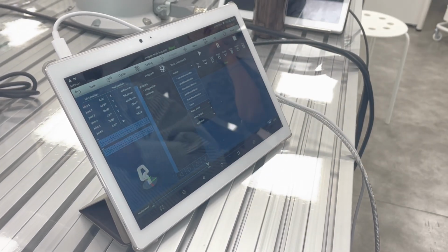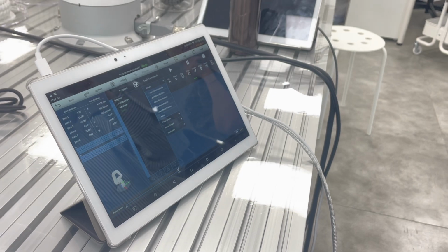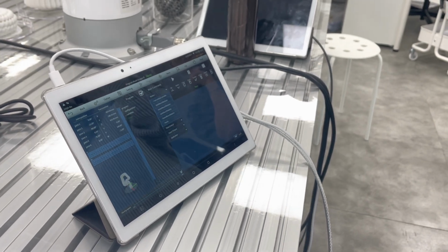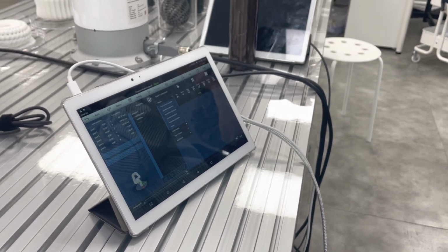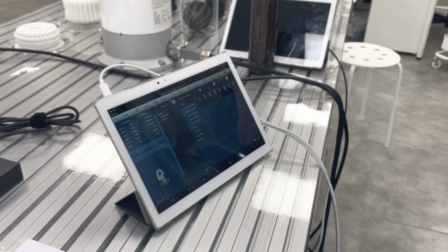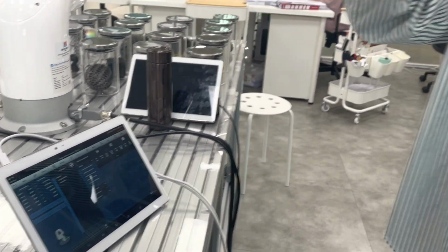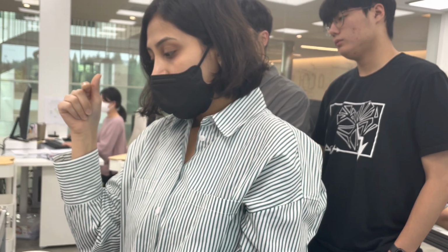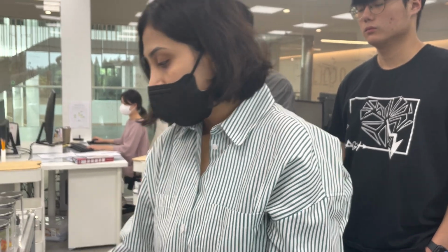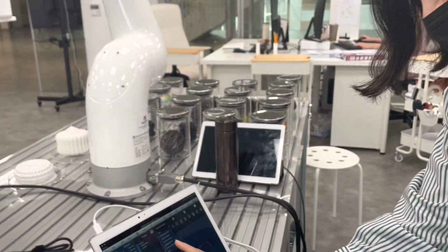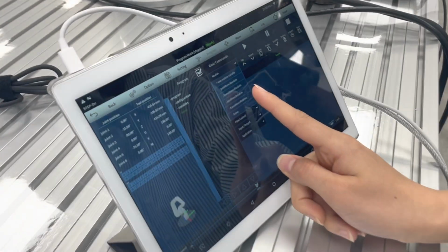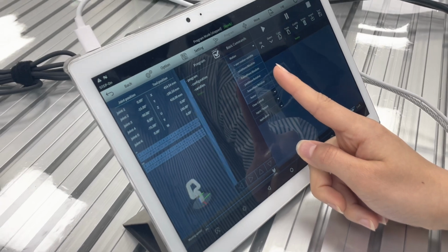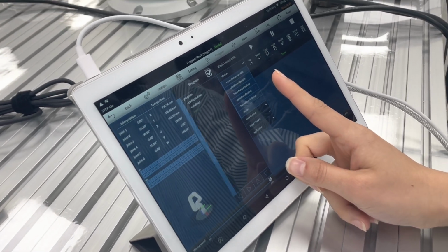By absolute, it means that when we set a point, we are telling the robot to move exactly to a certain position. When it reaches it, no matter how many times we run the program again, it will not move because it reached the desired position. But if we set movements based on relative move, we are just telling the robot how much I want you to move.